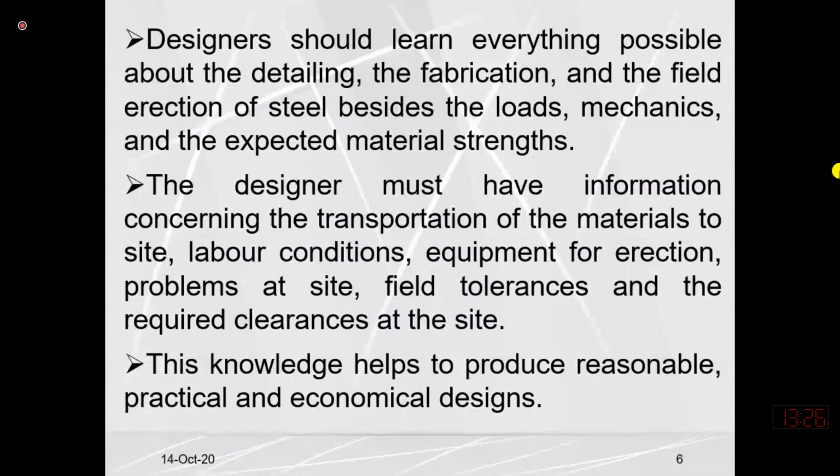So you have to think, can you transport this longest length of 10 meters or 30 feet to the site easily? We have to see the road clearance, maybe the truck size we need to transport with. If it is not possible, what we do is provide the beam in different spans. We will provide some interior supports and we can reduce the length of the plate girder. This knowledge helps to produce a reasonable, practical, and economical design.